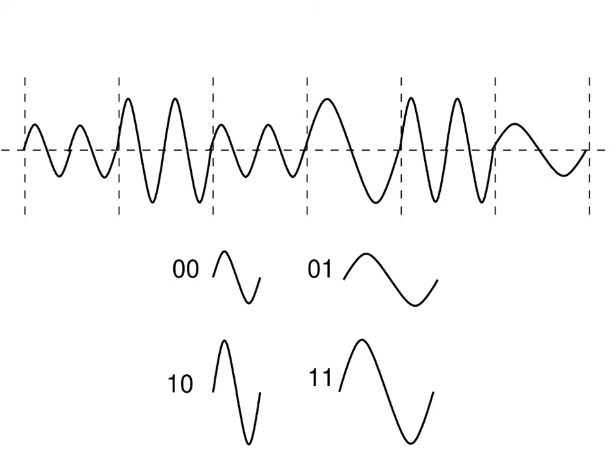What is it? It's a high frequency and a low amplitude compared to the others. It's in fact this one, which is a higher frequency than these two and a lower amplitude than these two. Which means that over this duration of 2 milliseconds, the 2 bits sent are 0, 0.